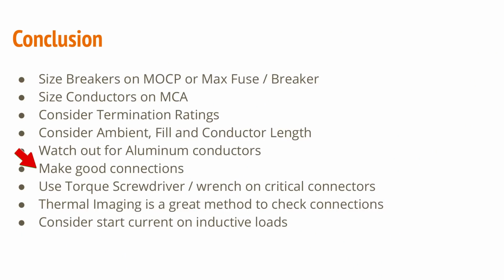Make sure all of your connections are tight. For really high critical connections, we really should be using a torque wrench or screwdriver. That's not going to be your typical residential. I mean, come on, nobody's doing that.